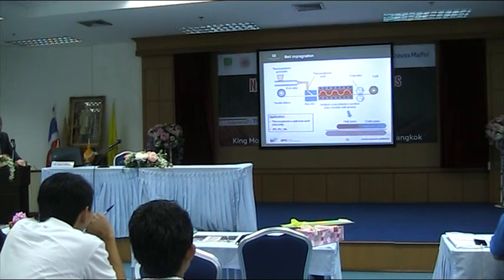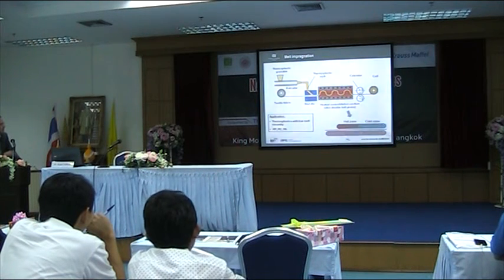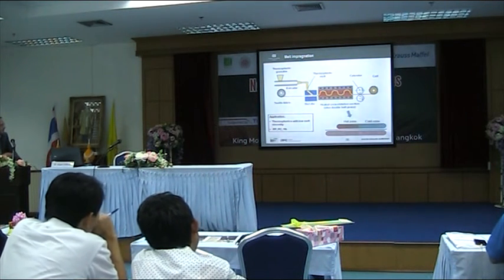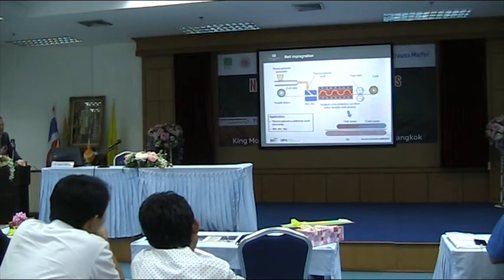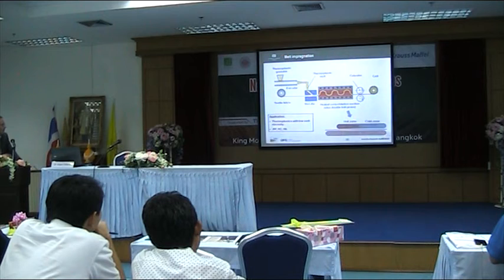As the professor already mentioned, it's really efficient. You have a roll to roll process for the prepregging process, and normally you use typical thermoplastic types, polypropylene, polycarbonate, polyamide, but also other technical materials.